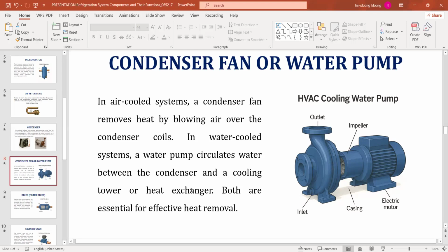So that takes me to those who, when you purchase a car, get brainwashed that you're supposed to remove the thermostat, that the thermostat is not for Nigeria and all those things. I don't think that is true, right? Your condenser fan in your automobile was not designed to work continuously. It was supposed to work when it's required, meaning it works and stops. The reason why some people who alter their fan and put it in direct have issues with overheating is that the fan is running continuously.